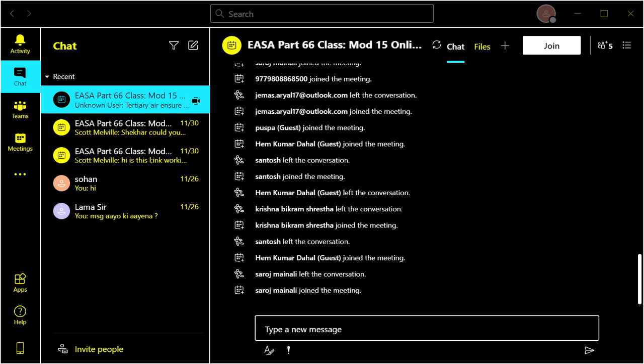This sort of kit, which is called a patch test kit, just for your own background information: we would get a sample of oil, dilute it with a special fluid, and then we get one of these little filters, put it in here, and we'd vacuum pump it through, and it would give a colour. And we have a chart, represented by this chart here, and depending on the colour, it would tell us exactly what was acceptable, what was not acceptable. We thought there was maybe some fuel in the system. It was basically like different greys, colours of greys and tans, and we could tell you what was wrong with it. Again, you need specialist training before you use this equipment.